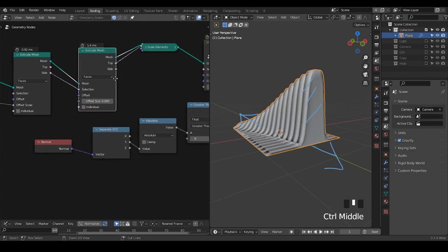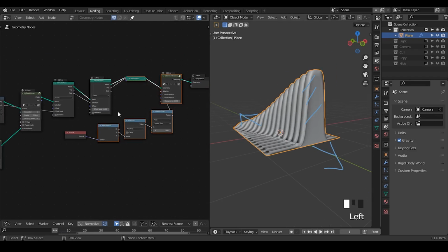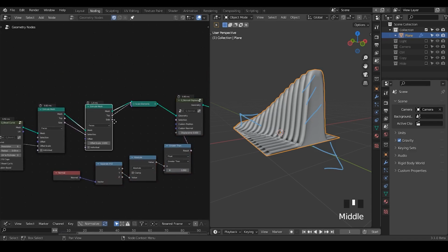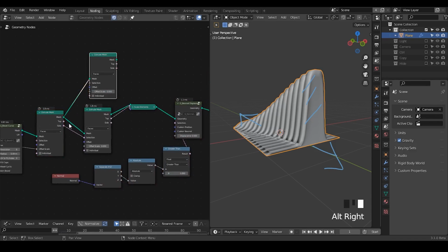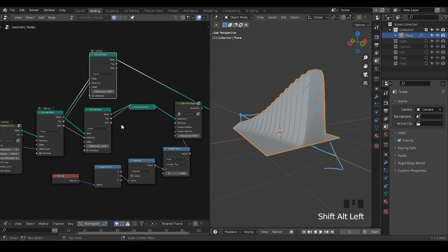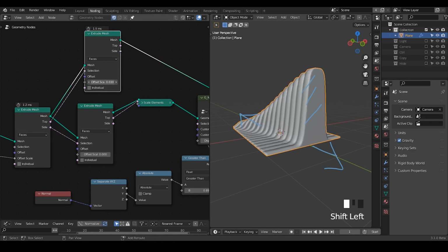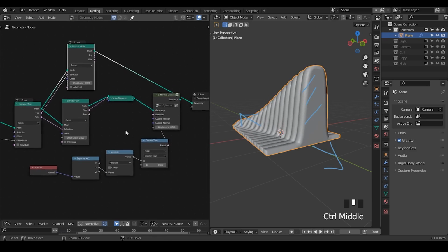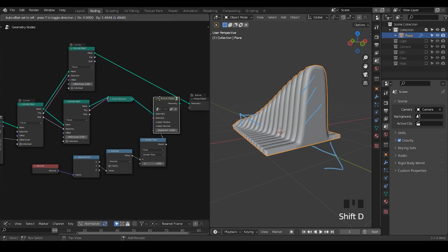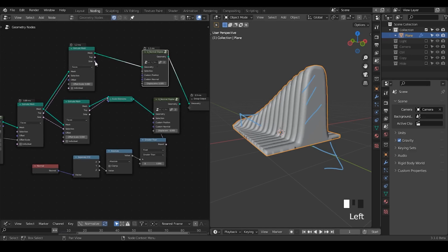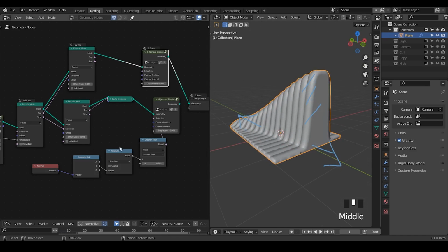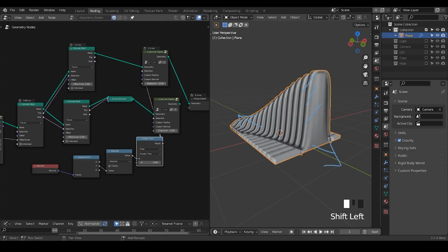For example, perhaps we can inset the top, extrude the top part. So for example, let me see. Yeah. So this is also a way. I think this way is actually better because we are adding the thickness. And then we just normal displacement with the original, we still use the same selection. Let's see how it has.